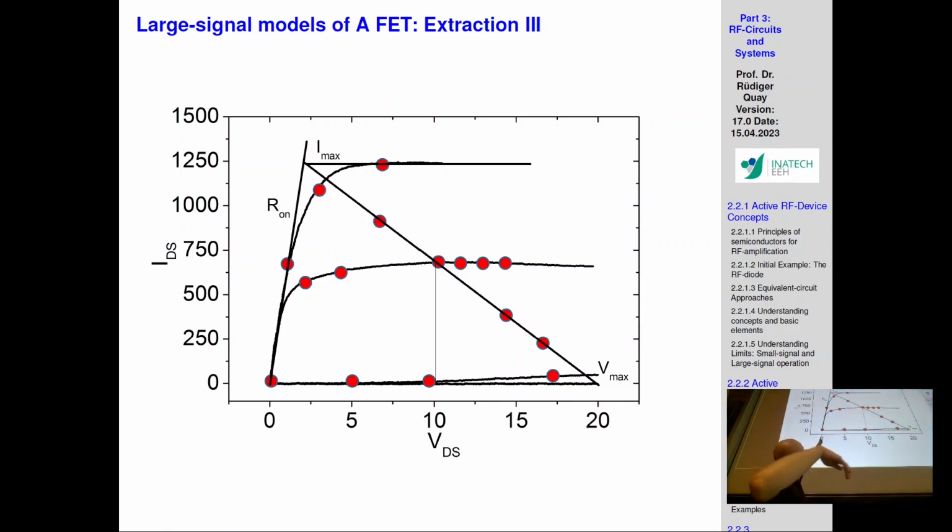I think you're all familiar with, right, the cutoff region, the linear region, the saturation region, and then you have a compression and breakdown region. And before here, you would have this kind of curve. You would have the drain source current with respect to gate source voltage, and you expect every time you increase the gate source voltage, now here in the horizontal you have drain source, obviously, but if you're imagining these steps to be the increase of the gate source voltage, you think in your head, okay, increasing my gate source voltage should increase my drain source current, and my curve should be linear, right?